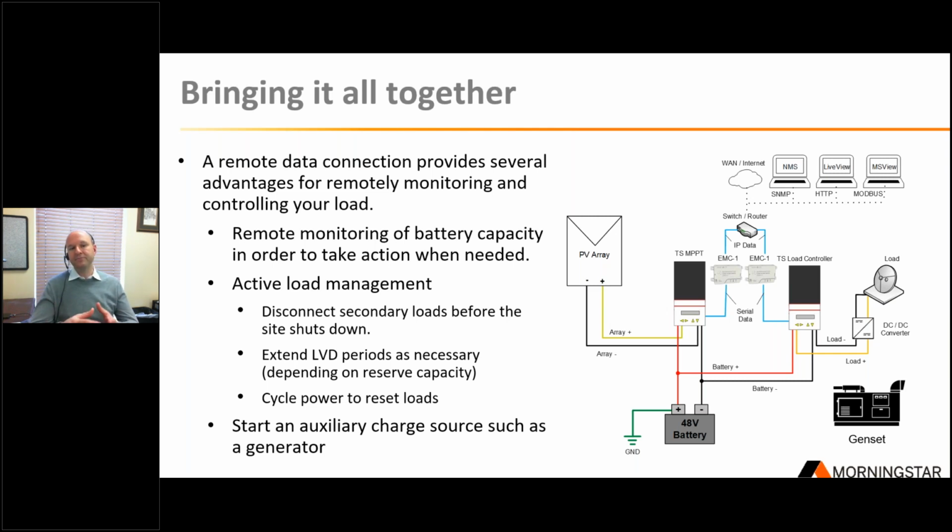So in these systems, LVD is not an option. Before you have an LVD, you turn the generator on to consume some fuel. And at a lot of these sites, diesel, maybe even propane for longer life, they can keep that LVD from ever occurring. And I often refer to this as active load management. Someone actually connecting to a site, seeing what's happening, monitoring this, disconnecting non-primary loads to save power, starting a generator, staving off an LVD situation.